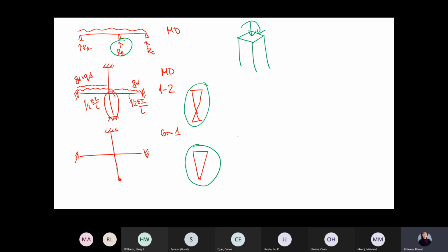This procedure is very straightforward. Okay, so you need to determine your L effective. You have a whole lecture on this, so you have a handout. The steps are something like probably 5-6 calculations, nothing complicated. You just have to, of course, show me that you understand what you're doing. So L effective, in order to calculate your lambda and compare it with your lambda limiting.